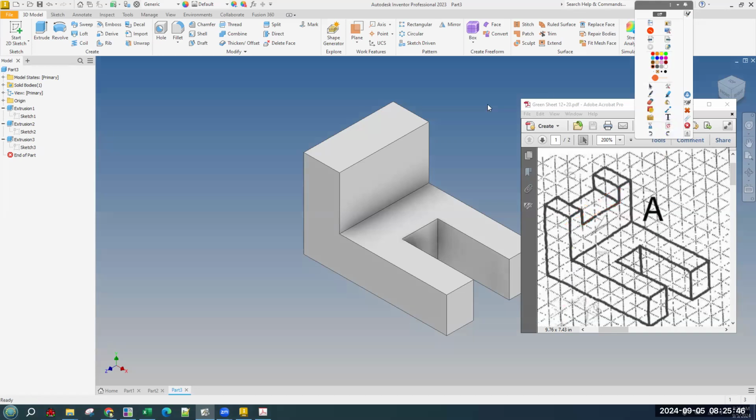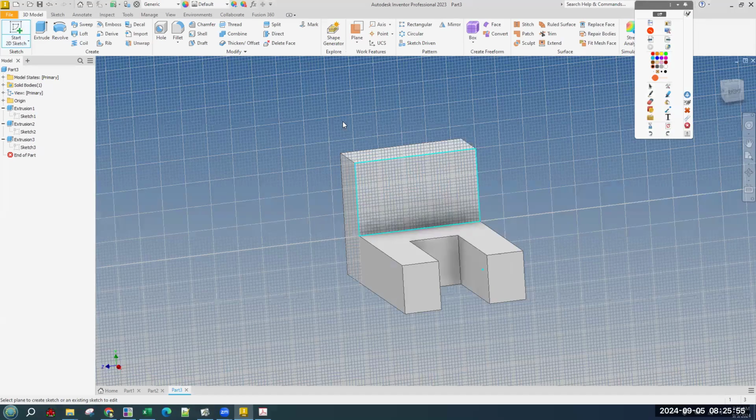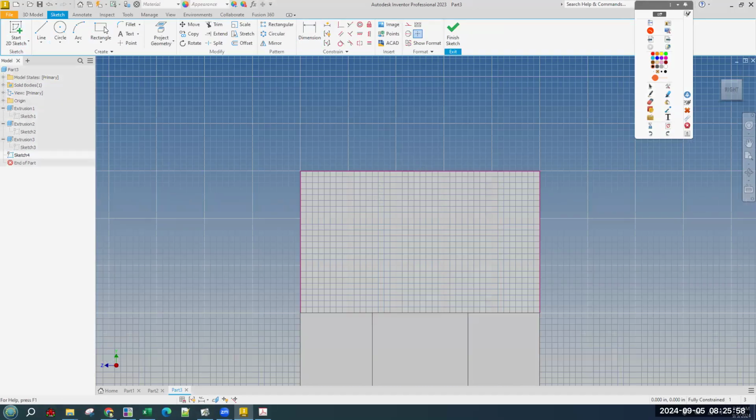But you will see. If that was confusing, you're normal. And so we need a new sketch, and we're going to sketch on this face of our part. It'll snap to, should show it to us. Rectangle tool, snap to the top edge, but again, not the center point or the corner, just that soft snap on the edge of the face. And we want a rectangle. We know the rectangle is 1x3. We can go ahead and do that. 1 tall and 3 wide.